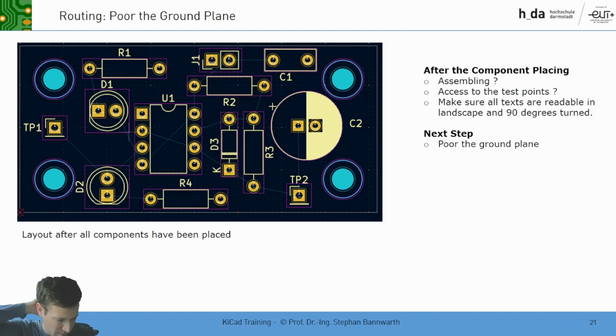But the thing you have to think about in the order of soldering is what is practical and good, and what is not so easy to solder. Check the access to the test points. This we just discussed. Since we have the screws here, we can access this test point very easily, and here too, between the two screws, we can access the test point also very easily.